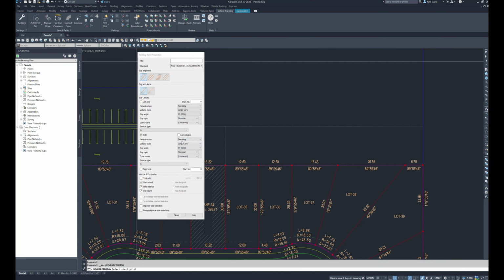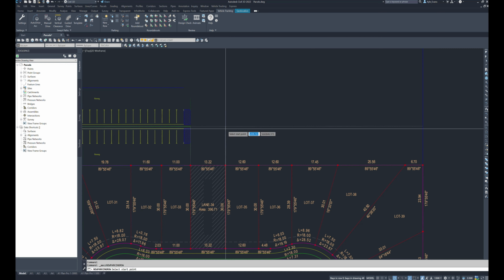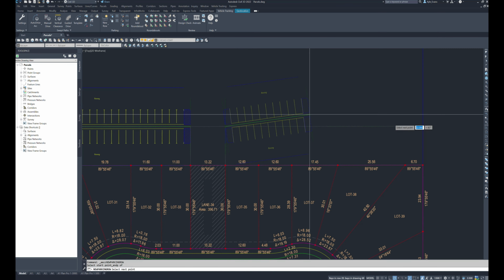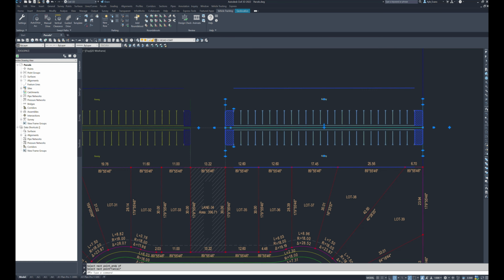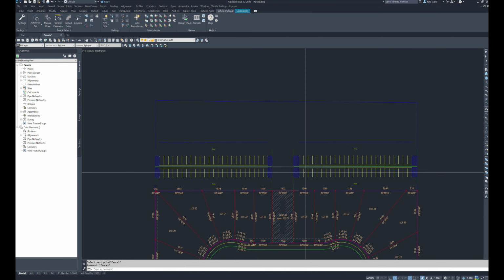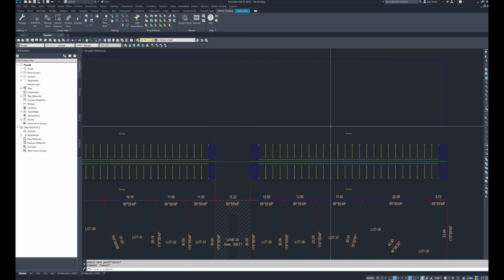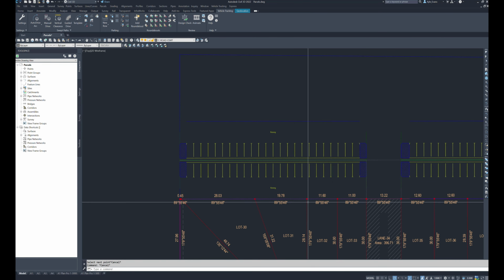The same parking standard. We can modify the options if we want. We're going to include another footpath, 1.5 meters wide. And I'm going to drag it all the way to the end here. Now, it is different distances on both sides, and that's perfectly okay.